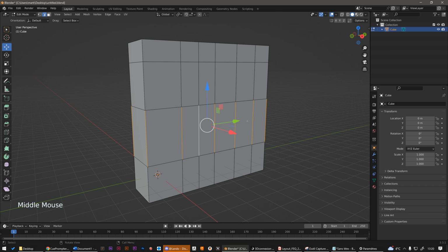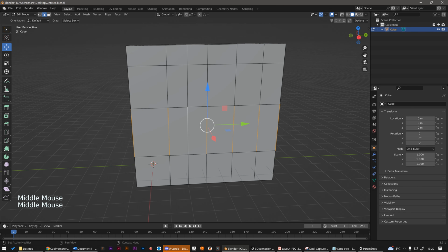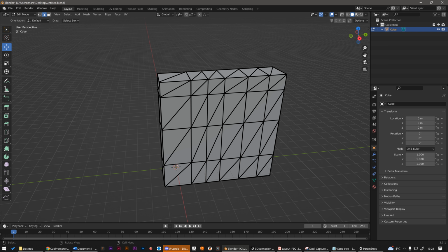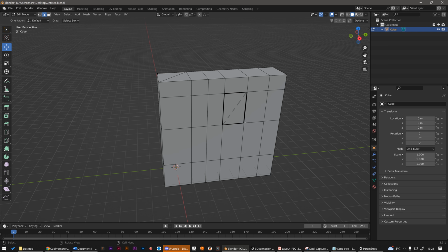So, to conclude about loops and rings, let's talk about the famous 3D modeling rule that you have probably heard: always work with quad faces. This is simply because a quad pattern is actually nothing but a network of loops and rings that make modeling much easier than using triangles. That's also why all polygon editing software, like Blender, display a quad face as a single face, even if for the computer a quad face is simply not possible, because a 3D face can be nothing but a triangle from a mathematical point of view. So, the software is cheating math for us by allowing us to work with square faces, which are actually two triangles merged.